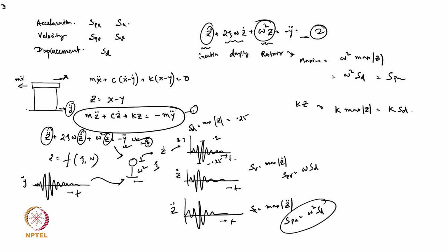Now if you think about the lateral stiffness contribution, suppose we come to the mass first. Mass mostly comes from the slabs. Columns maybe contribute some, but their weight is much lesser compared to the slab, so maybe some percentage. Foundation is not contributing mass for the floors.